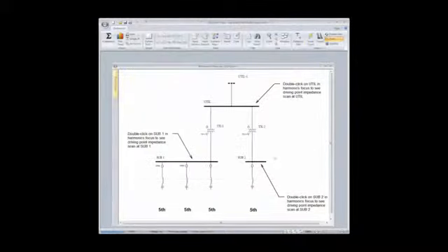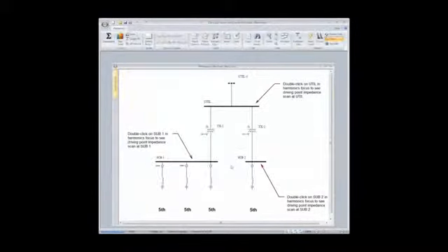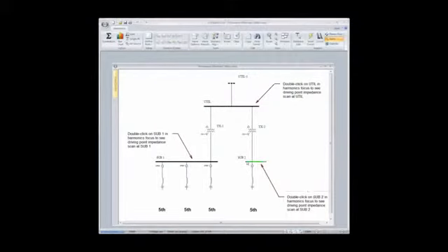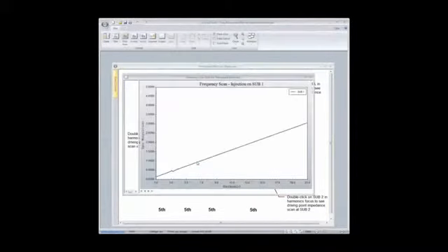And that's really important also if you're applying one over here. The effect of the other filter has been changed. It's modified as you're seeing it from this location. Let's do it another way. Let's unclick this filter, look at this bus, and whoops, that's that notch right there. And again, we see the nice fifth harmonic filter. From this location, what do we get?